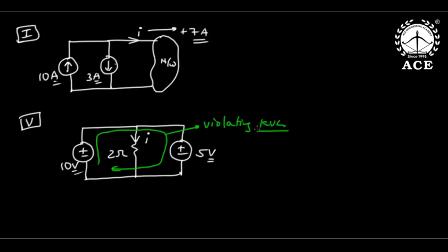But if you still insist on connecting two voltage sources in parallel, make sure that they are equal in magnitude and equal in polarity. In DC we can say, make sure that their magnitudes and polarity are the same.